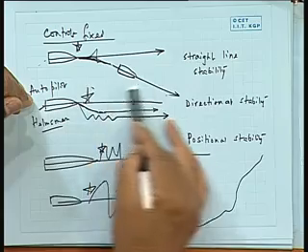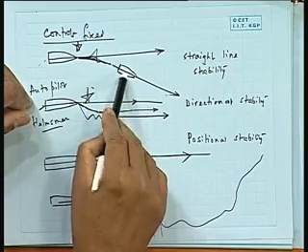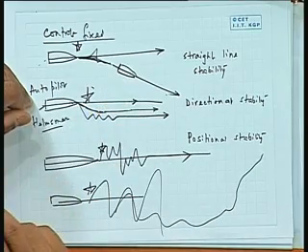Most ships you see, especially larger tankers, primarily go along a straight line, and only if you make a turn, you will make a turn with a large circle. So for large ships, you do not need very high maneuvering, quickly following, that you might need for a patrol craft or something. So this is the one that we will be talking about a little bit initially, and try to find out what characteristic is necessary to ensure that the ship possesses straight line stability, which of course can be done only in control fixed. Of course, I can also tell you that many ships in reality do not have straight line stability or have a slight lack of straight line stability.